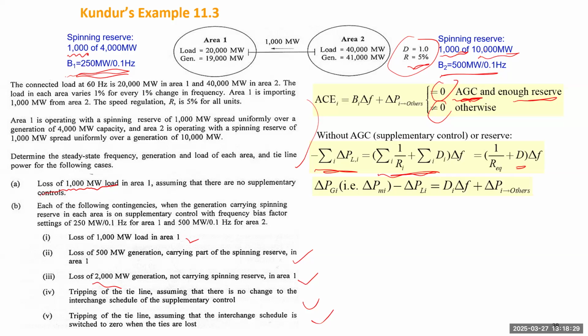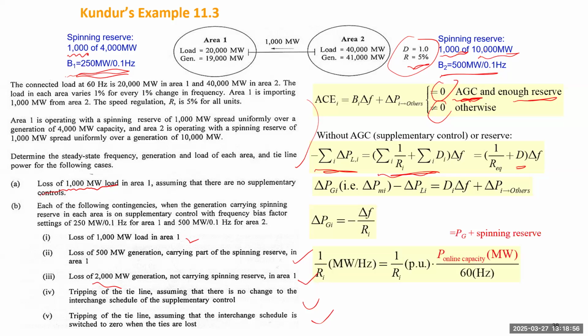Still based on the power balance. In this example, each generator's generation is called PG, which is basically just mechanical power. The left hand side is total generation change minus total load change. The right hand side will be the load change on the frequency dependent load and also tie line flow. This is based on the power balance. This is the droop control law.